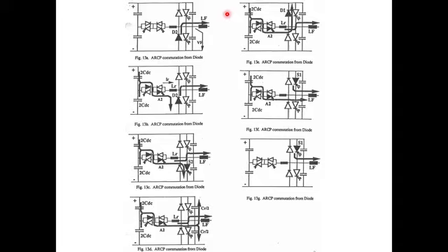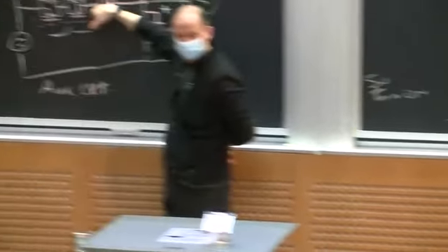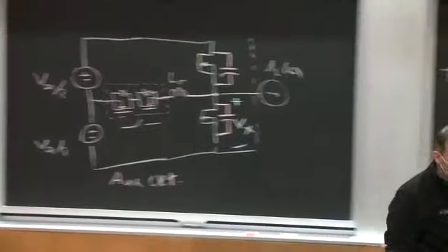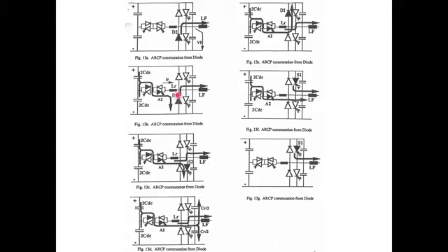He says, okay, let me trip on this auxiliary circuit. I'm going to close this switch with zero current switching. And what's going to happen is, because the bottom diode's on, current's going to ramp up in this resonant inductor. Then he's going to turn the bottom switch on at 0 voltage, because since this diode is conducting, he can turn this guy on at 0 voltage.